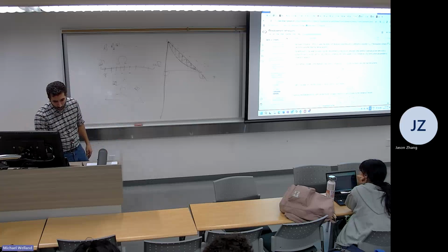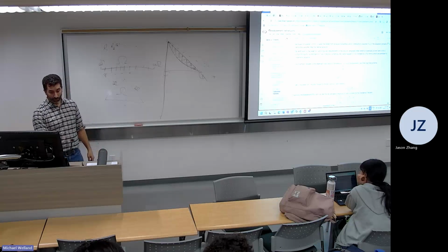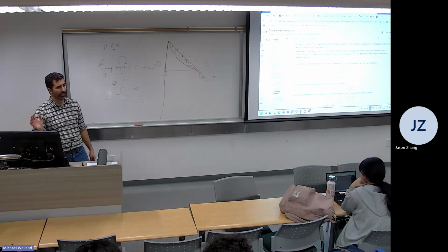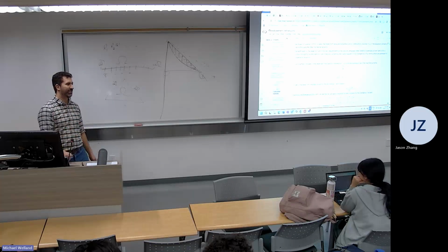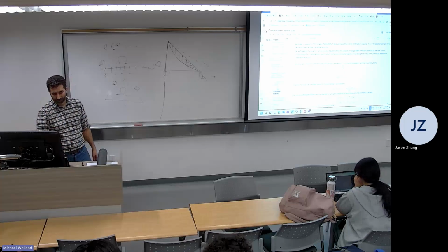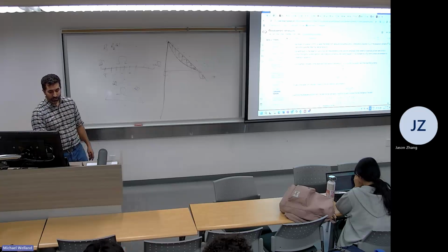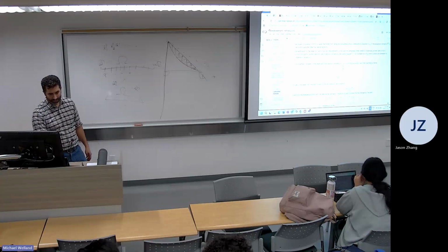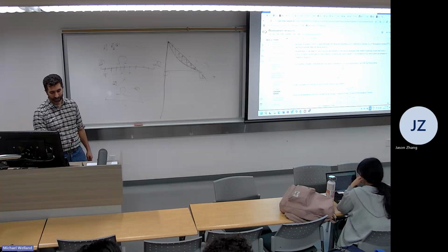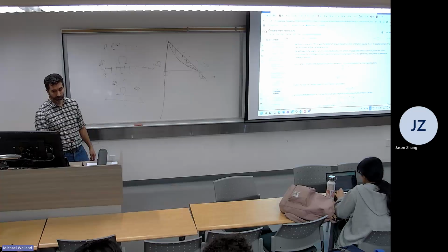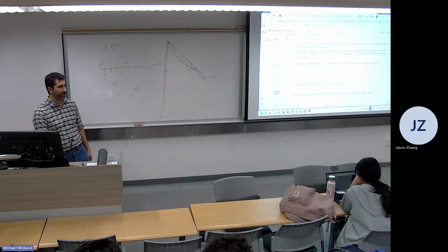As an example, consider the time-dependent heat balance. Here we're just using temperature equal to U. Some people actually do that, I think, to avoid the confusion with time. If time is T, then calling temperature capital T is a bit weird. Okay, and we're going to use a backward Euler time marching scheme. So what we say is this, no surprises, substitute in the Euler expression and rearrange. No problems here, okay? We're solving for U at the current time based on the previous time.